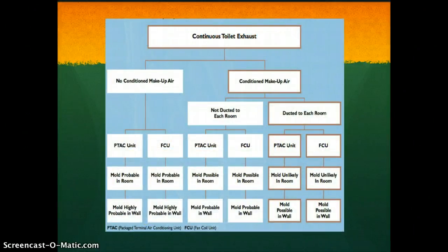This chart is adapted from the National Council of Architectural Registration Boards' The Hidden Risks of Green Buildings, Avoiding Moisture and Mold Problems, 2009. Figure 3.1 provides a flowchart of the predictability of moisture and mold problems in a hotel-type building with a series of heating, ventilation, air conditioning system choices, and an unforgiving wall system, such as a misplaced vapor retarder in conjunction with moisture sources. Other decision combinations can increase or decrease the risk.